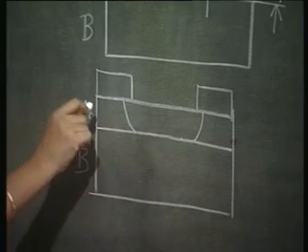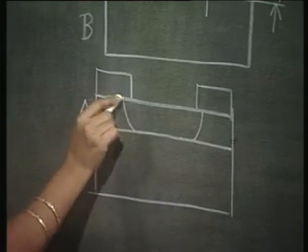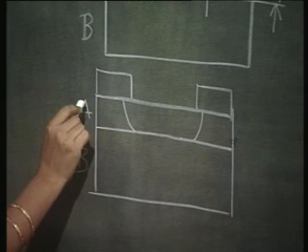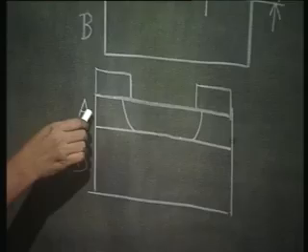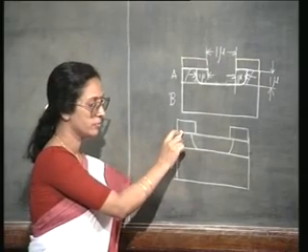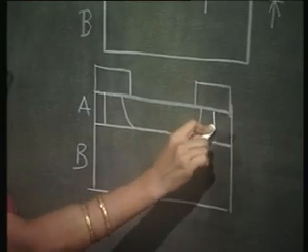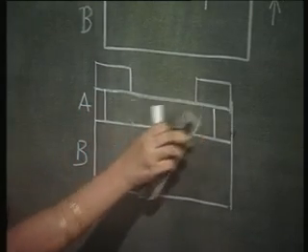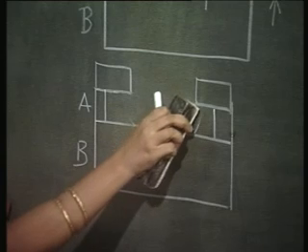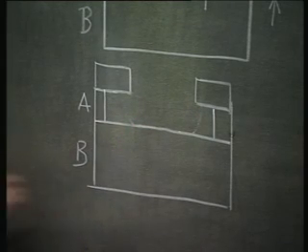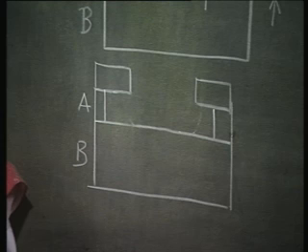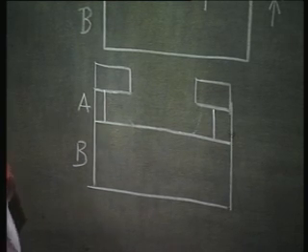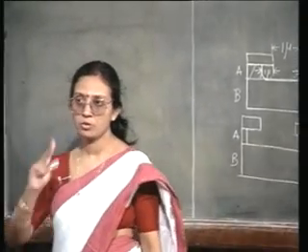And then since I have only the sidewall surfaces, etching will progress very fast on the sidewall, because now all the etchant solution is doing is etching the sidewall. So, I will have almost vertical sidewalls. Do you realize the problem? The problem is twofold.